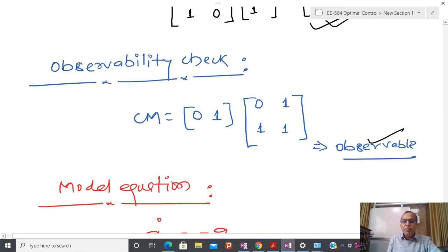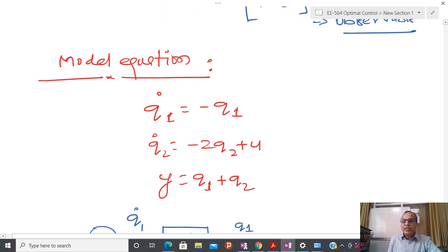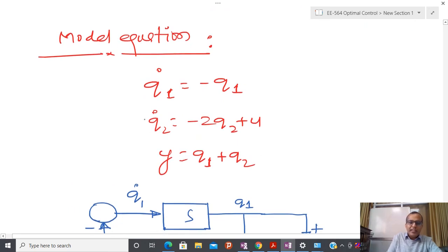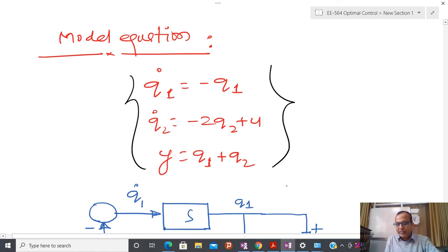And if you see the transformed coordinate frame, then things become more clear. So if you have nonlinear systems, try to do some kind of transformation. Particularly for some classes of nonlinear systems, it is possible to show that using Lie derivative or Lie bracket, it is possible to convert that system like this.